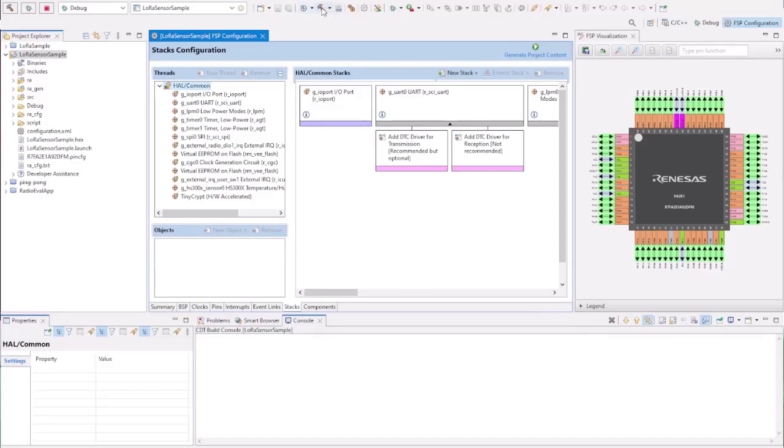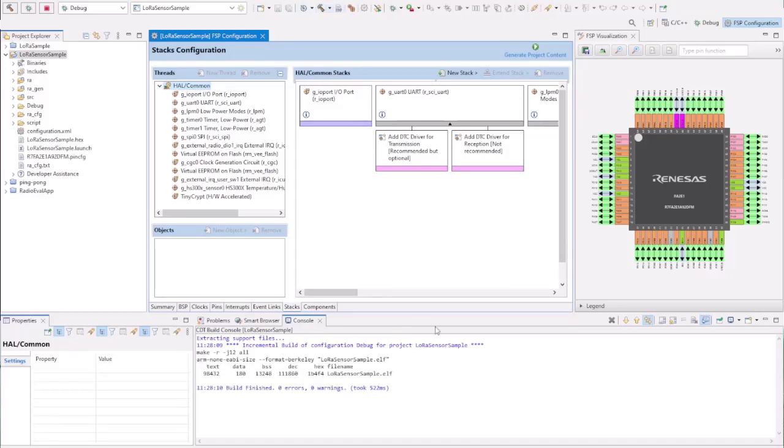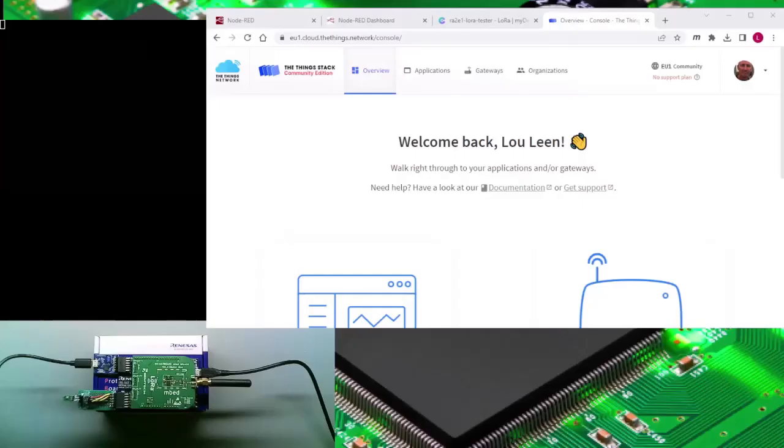First I will compile the project: 0 errors and 0 warnings, and I will subsequently program it into the target. Once I've connected it, press debug and it will load into the end target, which I have done in the meantime. And now you see the target down here